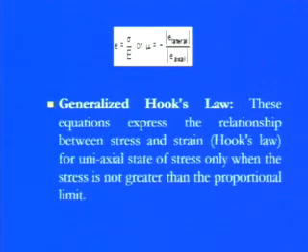After incorporating both properties, homogeneous as well as isotropic, we can say that the strains are proportional to stress. Strains we can easily measure using strain gauges or rosettes. Young's modulus, as we discussed, is a property of the material, so it has a different value for different materials. As we discussed in the previous case, there are 6 types of materials: perfectly rigid, perfectly elastic, perfectly plastic, elastic perfectly plastic, or elastic plastic. Based on that, the Young's modulus of elasticity has different values.